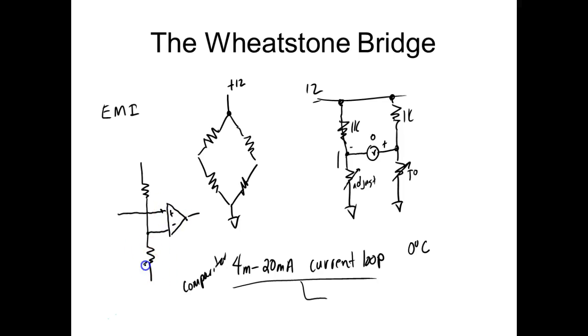So the way this thing works is I come up here and I set a voltage with this guy. Let's say I set +3 volts. And then what happens, as long as this right here is below 3 volts, the output would be 0 volts. And as soon as it clears +3, so let's say 3.1, then this output would go to whatever powers up the comparator.